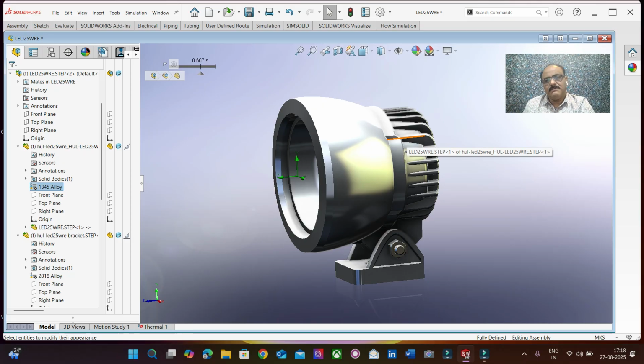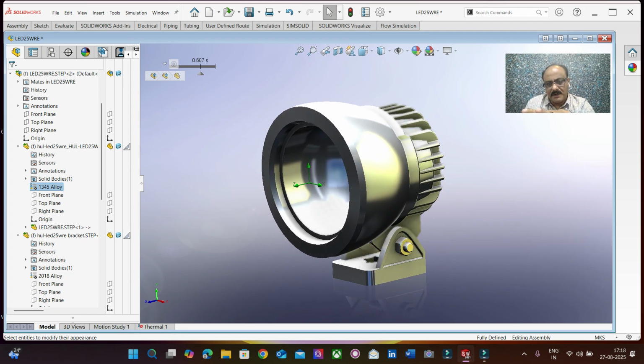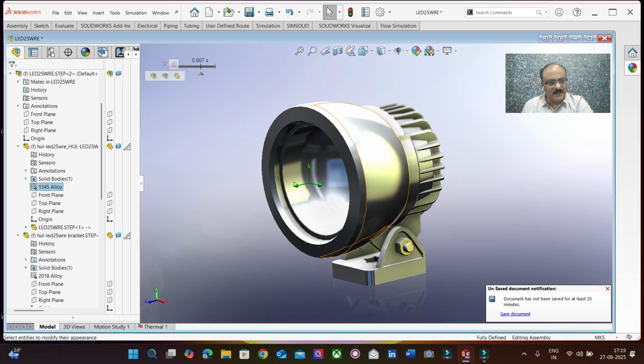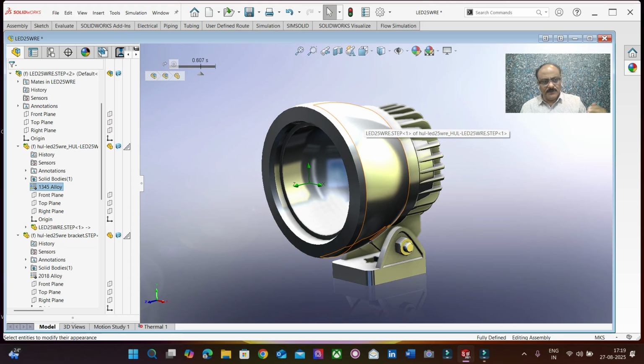Okay, so now here it's a computational fluid dynamic system. So immediately the software will try to solve, it will try to bring in a set of Navier-Stokes equations, and then it will start manipulating the flow equations based on the inputs we are providing. We are going to give what the airflow velocity is going to be, and based on that airflow, it is going to identify whether this is going to be external aerodynamics. Okay, so these are all the parameters we are going to give. We can find it here.